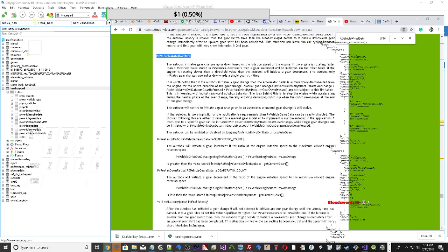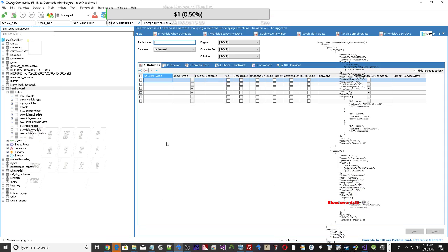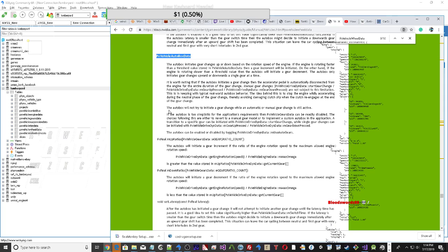The purpose of the Physics Vehicle SDK update function is to compute suspension and tire forces using the sprung mass model, and then to apply the aggregate of these forces to the Physics SDK rigid body representation in the form of a modified velocity and angular velocity. Interaction of the rigid body actor with other scene objects and global pose update is then managed by the Physics SDK. The update of each vehicle begins with a raycast for each suspension line. The raycast starts just above the top of the tire at maximum compression and casts downwards along the direction of suspension travel to a position just below the bottom of the tire at maximum droop. This is shown in the diagram below.